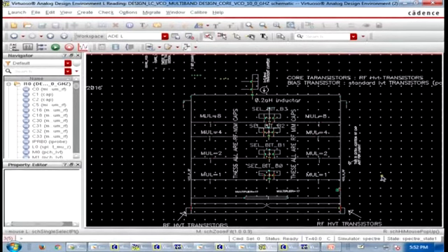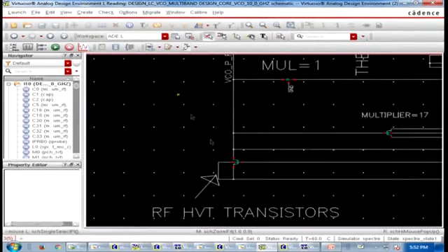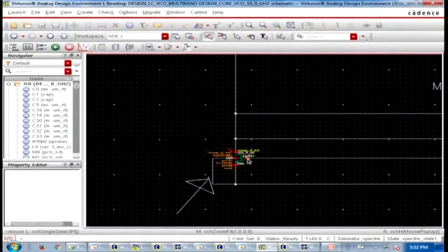Secondly, if you look at this cross coupled pair, you can see this is the drain node. The drain node has the drain to bulk capacitance as well as the drain to gate overlap capacitance. This drain to gate overlap and drain bulk capacitance will come into the picture along with your MOS varactor, so your frequency of operation will come down. So if you have to increase the frequency of operation, what do you have to do?